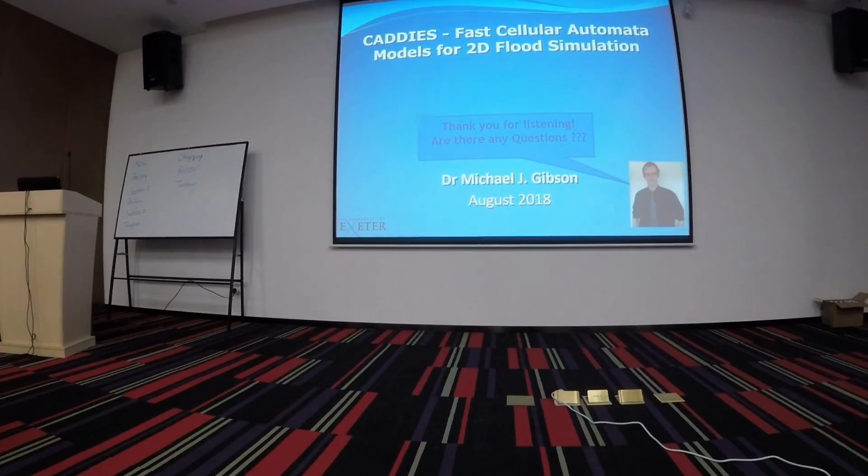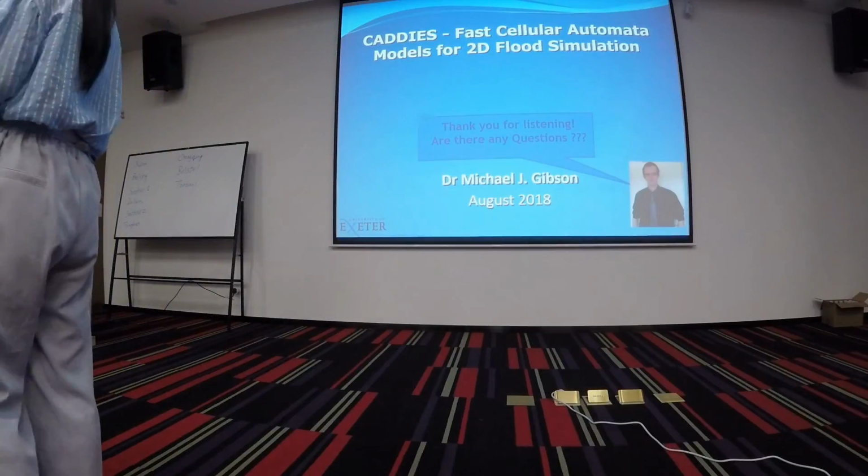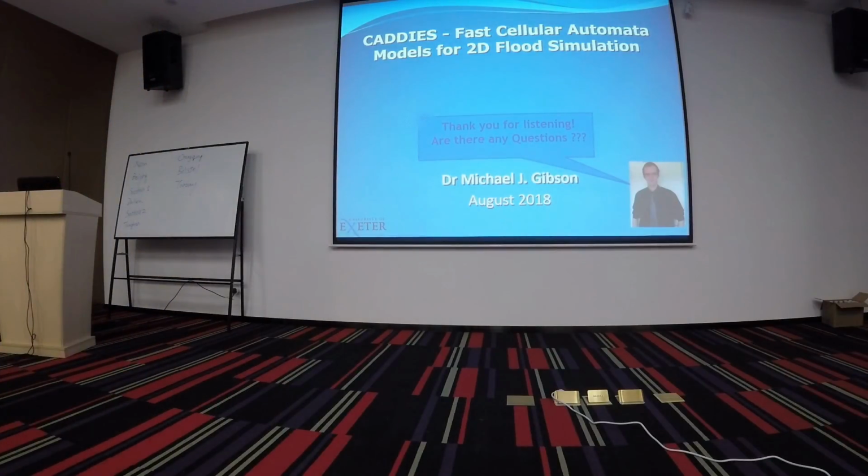Do you see the run from the roof, and how a cell is taken up by the building only maybe 50%? How do you consider this? Okay. First, it depends on how you make that mask. The mask is a raster. So once you convert your building polygons into a raster, that's the point at which you decide whether a cell is inside or outside the building. So it depends on your polygonization algorithm. The other part is how you set the building height. Are you going to set it to 20 centimeters or 3 meters? Either way, the building is a surface that water can be on. So if you've got it at 3 meters, it's on the roof and can flow off the roof. Does that answer your question?